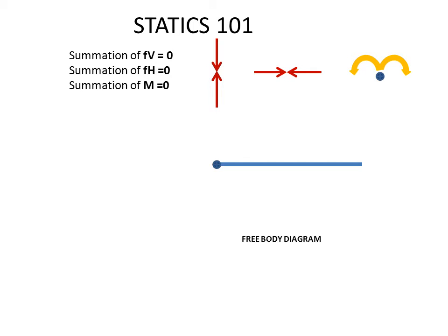Here is a lever arm emerging from a center point on the left side. We are going to apply a moment of 1 foot-pound on this node. The length of the lever arm, hypothetically for this problem, will be 1 foot. Even I can do this math. Thus, in order to achieve 1 foot-pound of moment, we will need to apply a force of 1 pound to the end of the lever arm to achieve the counteracting moment of 1 foot-pound in order to keep the free body diagram static, thus not rotating in space.